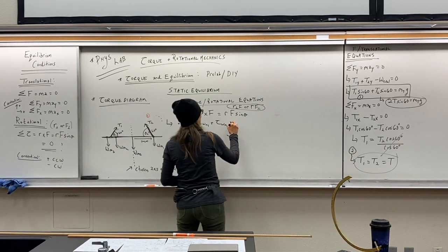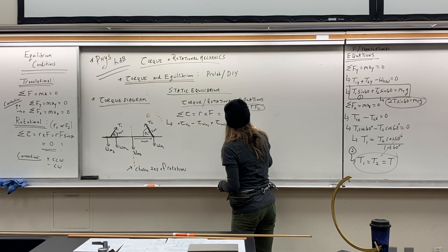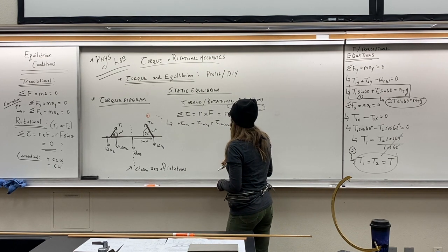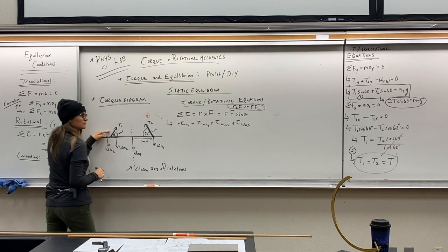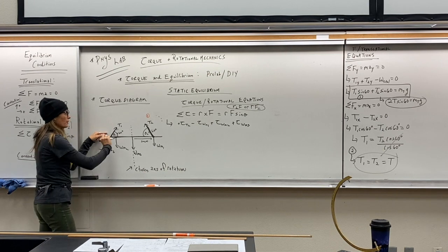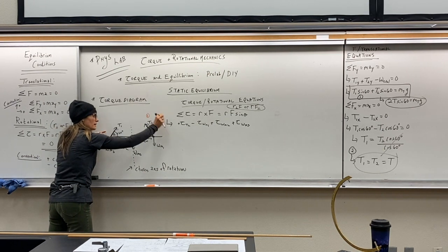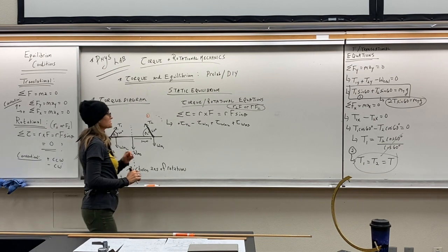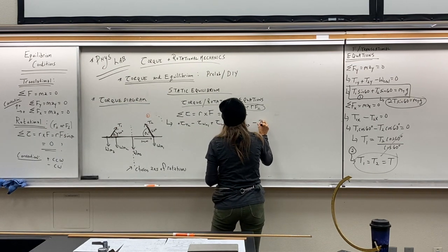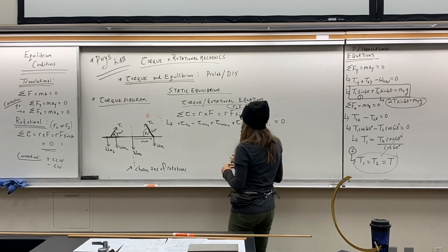So I'd say plus the torque caused by the weight of mass 3. Okay. And then finally, the last force that we need to account the torque for is T1, and that would produce a clockwise motion in that direction. So we'll say minus the torque due to T1, this should all sum up to 0.